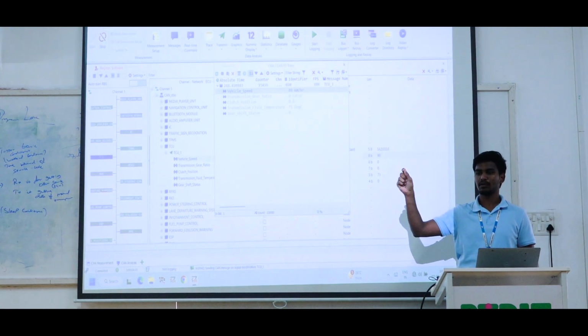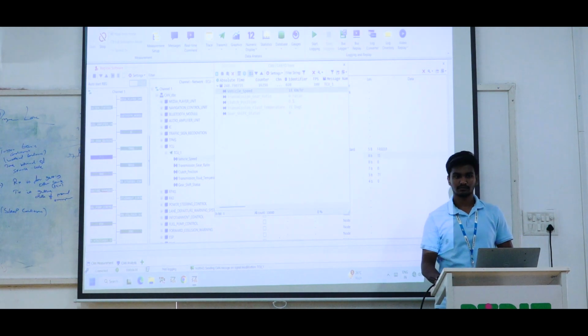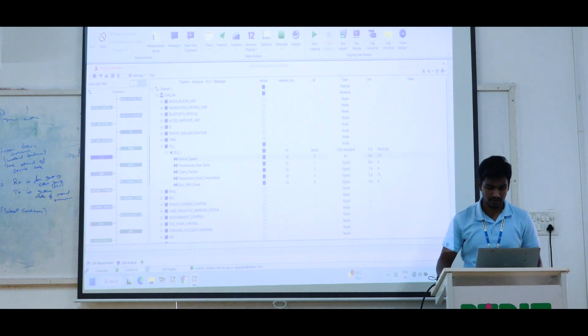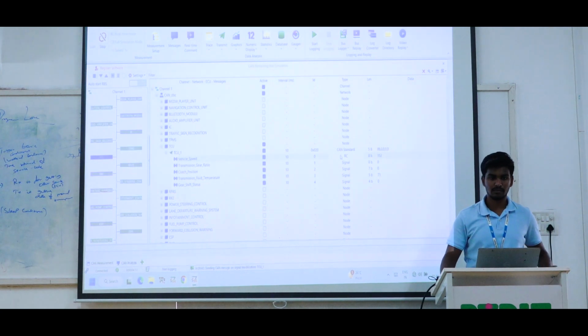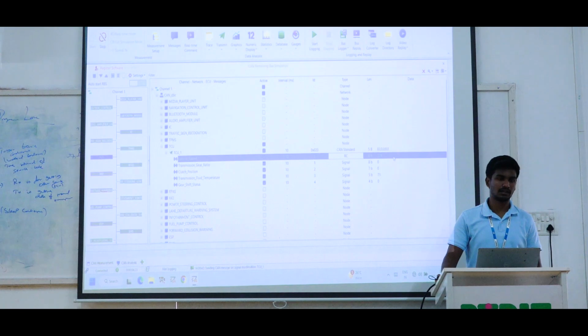So it is taking the time of 10 milliseconds, 100 milliseconds to hold the values. How to give rolling counter? So in this RC, which means RBS, just click any one of the signal. For example, we can click the RC vehicle speed. On the right click, it is asking for set RC. So you just give this, and automatically it is handling.